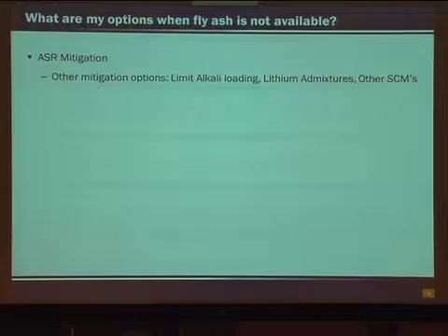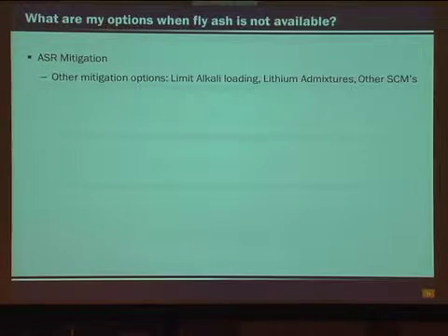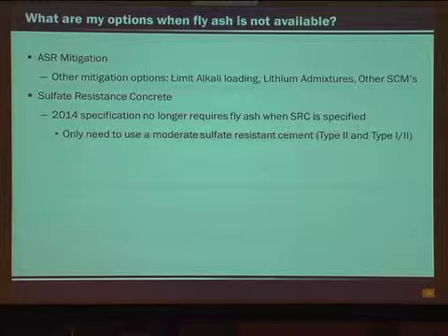All right, what are your options? Other mitigation options? Lithium, other SCMs? Well, we don't have other SCMs in Texas, so that's not a viable option. Lithium's expensive, so really the only one is straight cement and lower alkali loading. That's really all we could do.